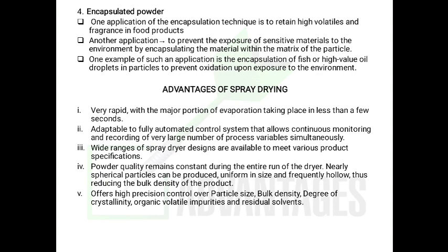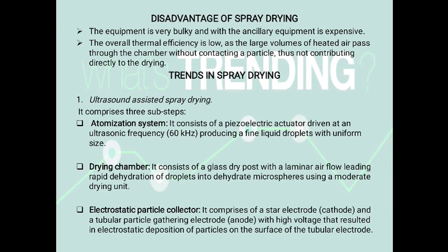Nearly spherical particles can be produced, uniform in size and frequently hollow, thus reducing the bulk density of the particle or the product. It offers high precision control over particle size, bulk density, degree of crystallinity, organic volatile impurities, and residual solvents. Disadvantages of spray drying.